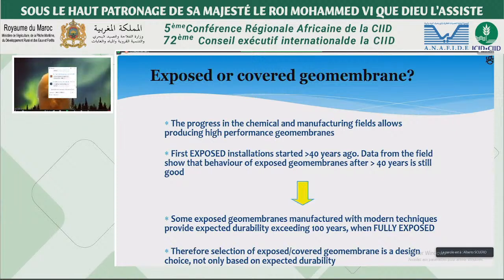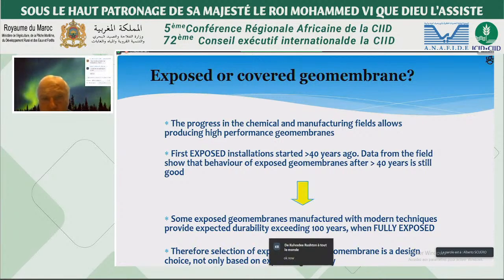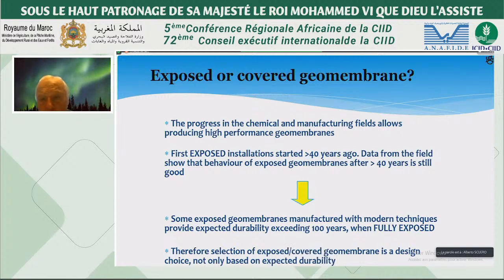Big question: expose or cover a geomembrane? The progress in the chemical and manufacturing fields allows producing high-performance geomembranes. First exposed installation started more than 40 years ago. Data from the field showed that behavior of exposed geomembranes after more than 40 years is still good. Some exposed geomembranes manufactured today with modern techniques provide expected durability exceeding 100 years when fully exposed. Therefore, selection of exposed or covered geomembrane is a design choice, not only based on expected durability.